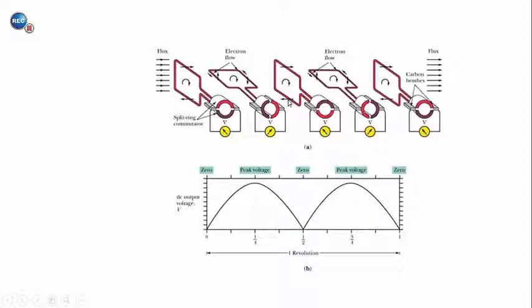And so at 1/4 of a turn, this part of the conductor connected to the red commutator was on the right brush, and so as this conductor moved down through the flux, the current was induced into the page. So the current was flowing into the page on the right through the coil and out of the page on the left. And so the current through the voltmeter is from left to right.